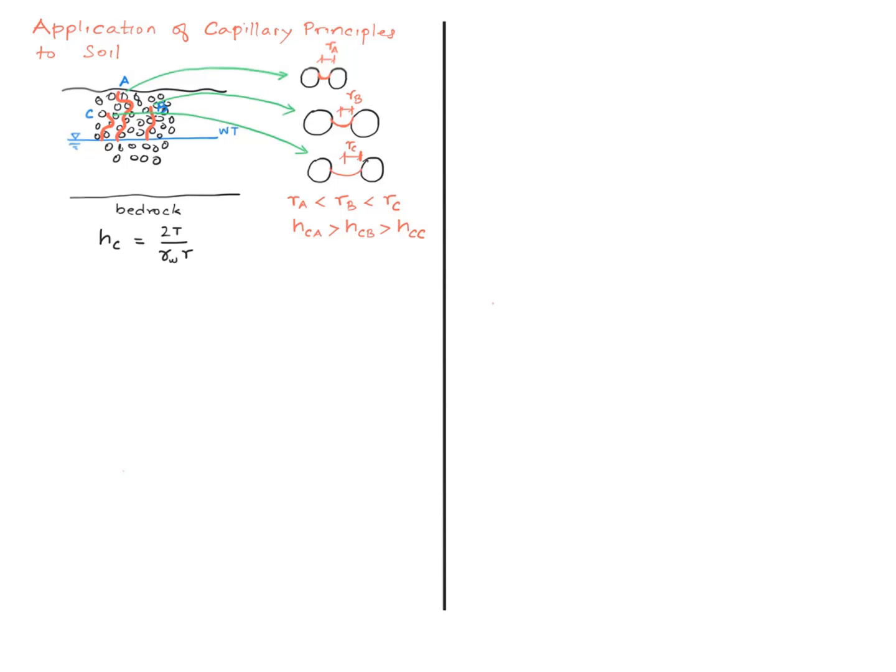So the capillary water is going to rise as high as it can be sustained by the surface tension. The equation we derived earlier shows that the capillary height is inversely proportional to the radius of the capillary tube. And therefore, in tubes with smaller diameter, the height is going to be bigger.